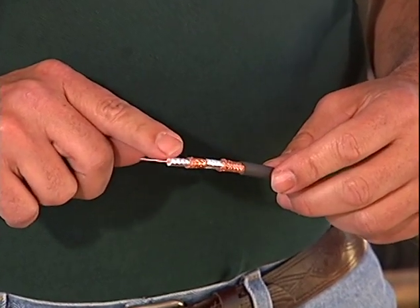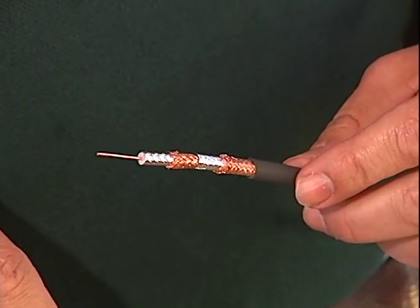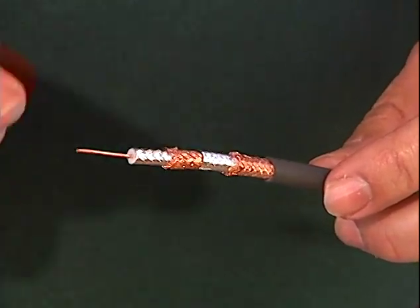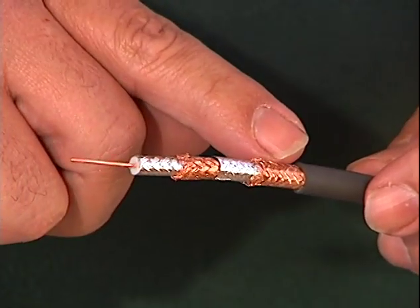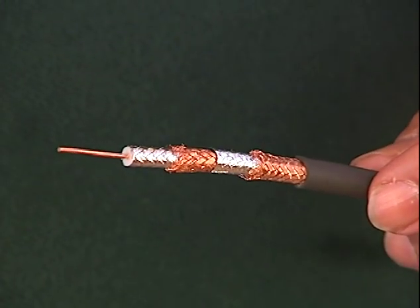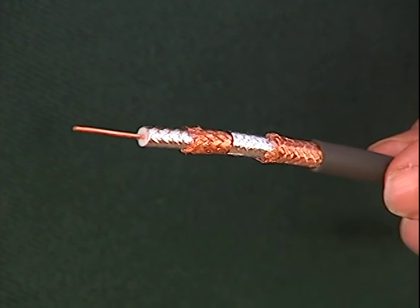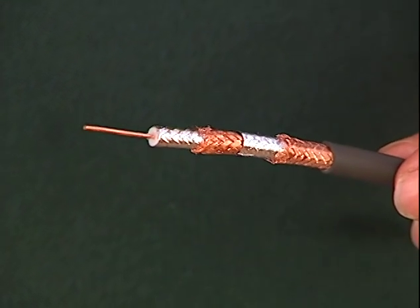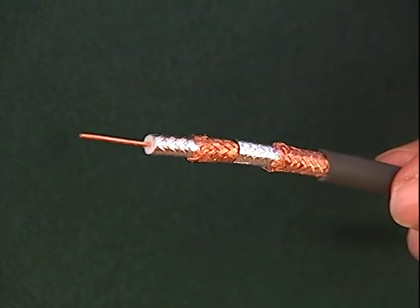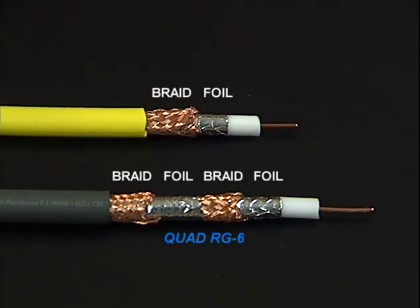Shields come in two varieties. Foil, where aluminum is bonded to both sides of a plastic tape to provide 100% coverage, and the braid, where flexible wire is woven around the dielectric. Braid coverage is usually less than 85%. The foil provides 99% of the ingress protection, while the braid is used primarily for strength to prevent breakage of the fragile foil. You can purchase RG6 with one braid shield, a foil and braid, a foil braid foil, and a quad shield, foil braid foil braid.